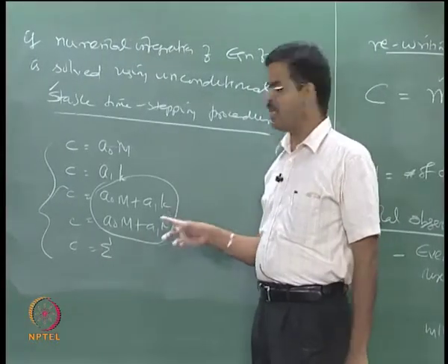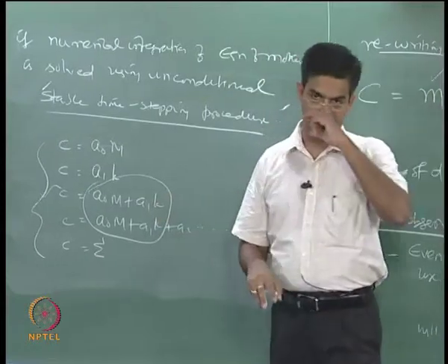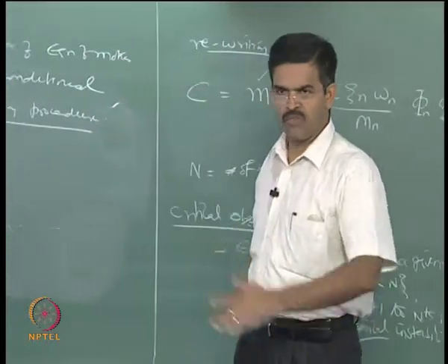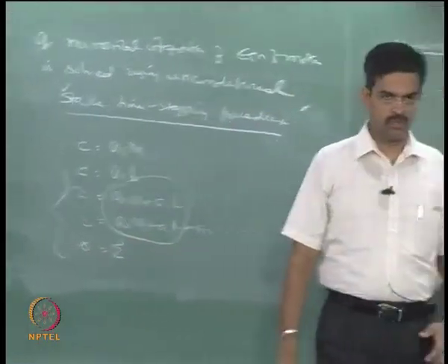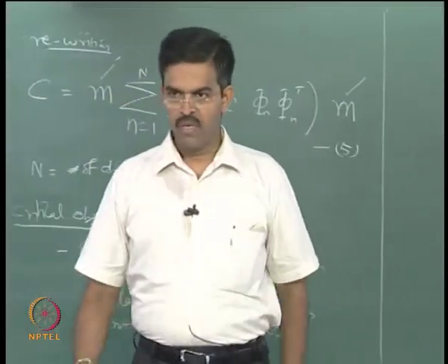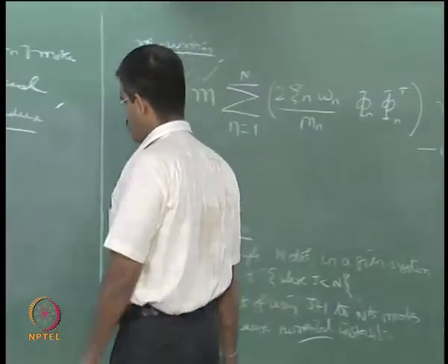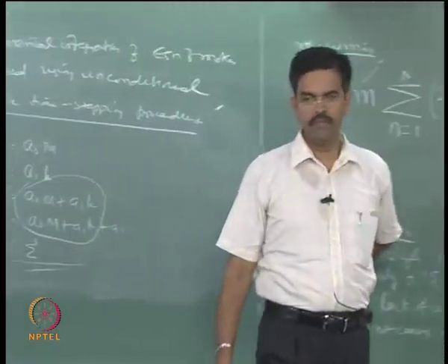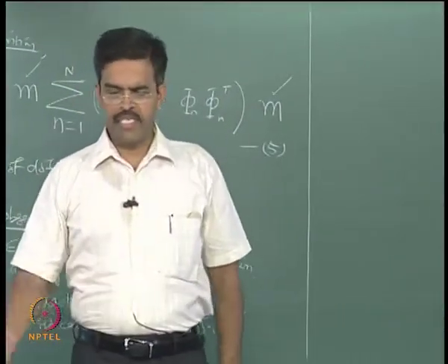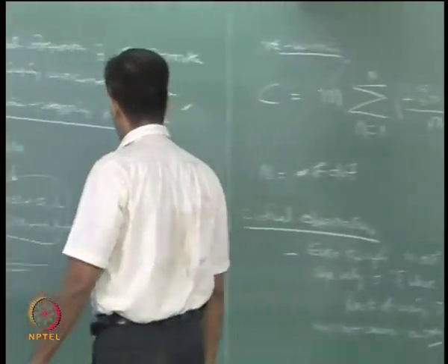That is why you will see in most offshore structure problems people use Rayleigh damping. There is nothing like discouragement, and many of them, if you see intelligently, have used modal superposition. Many papers would use this. Many land based structures, onshore structure problems, will usually be solved with this. So, there are many varieties of applications and preferences given by the researchers for solving different kinds of problems.